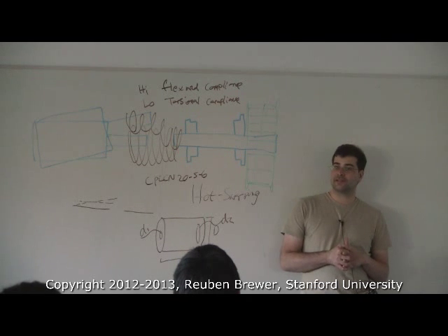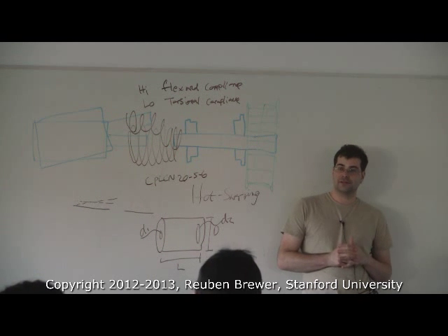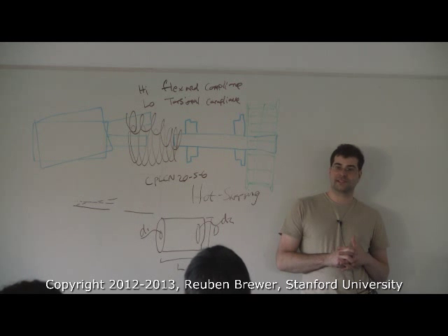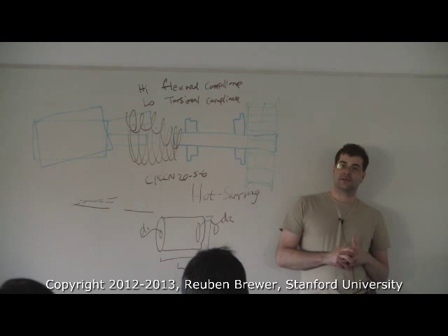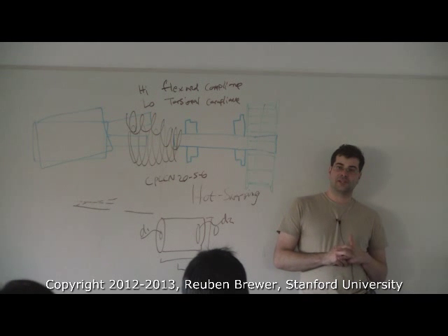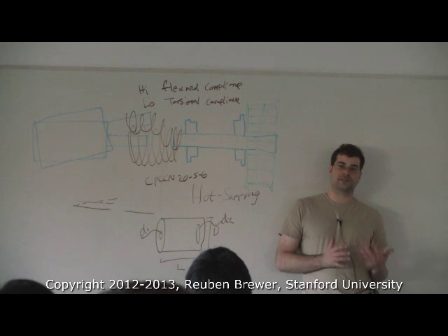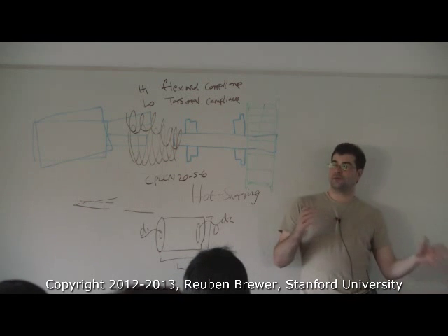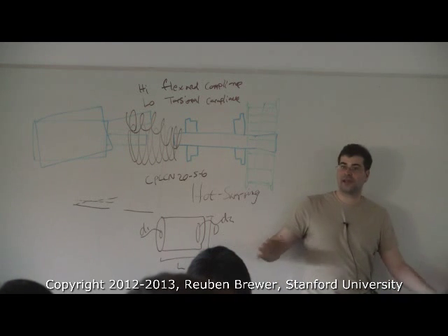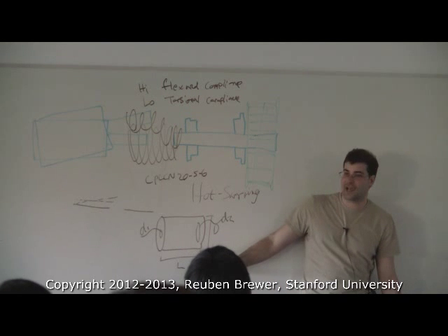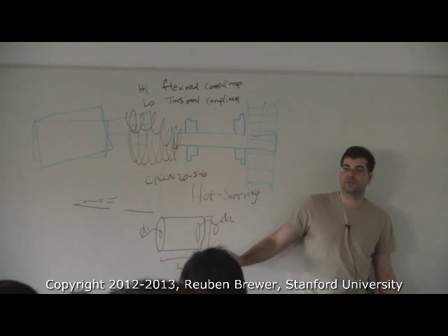Now, another hint, a lot of these little miniature robot things, the set screws are tiny. I've used M1.6 set screws. I've used M2 set screws. They all strip, they all suck. And it's one of these things where you think it's going to be okay in CAD, but then you spend literally a week of your time doing nothing but dealing with set screws, and you're like, wow, this sucks. So I considered giving you a lab that tortured you with set screw couplers, but I'm going to save you the effort. Just don't do it. It's as bad as having to sand shafts or use 0.5 millimeter stack shims.